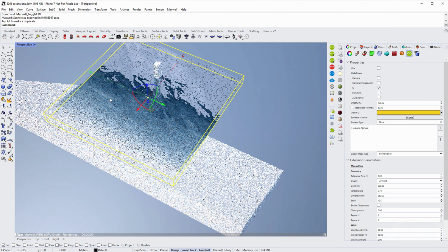So let's make this show more blades. Okay, now it's showing 100%, and it will display 10,000 blades. Let's change it to shaded, for example, and now you can get a good idea of what's happening with the blades here. And you can, for example, start tuning this.